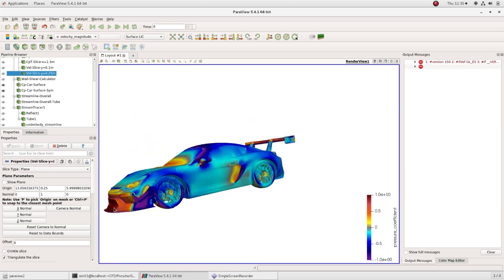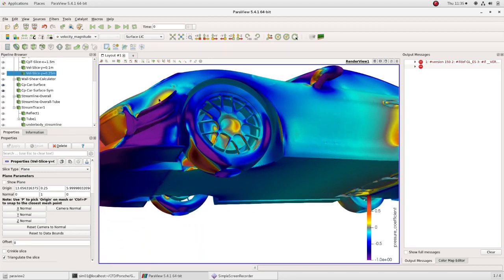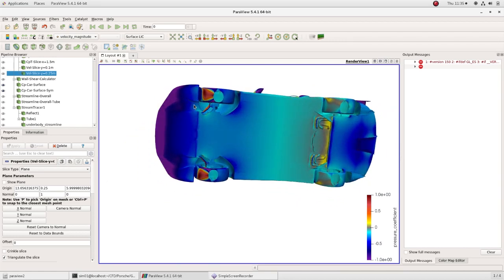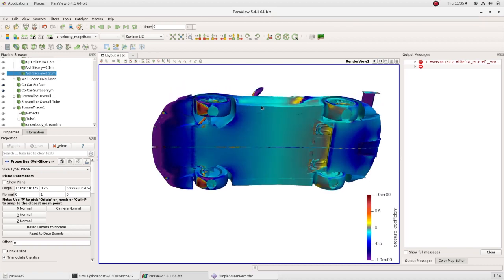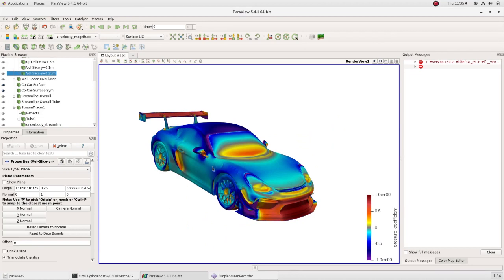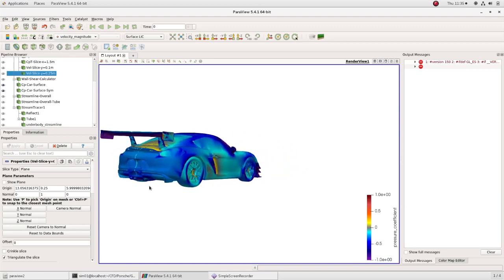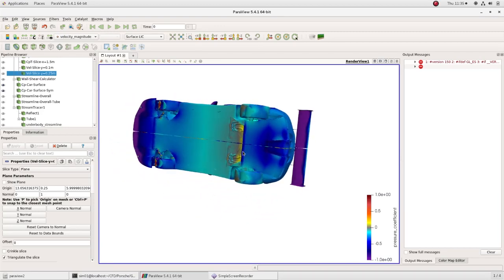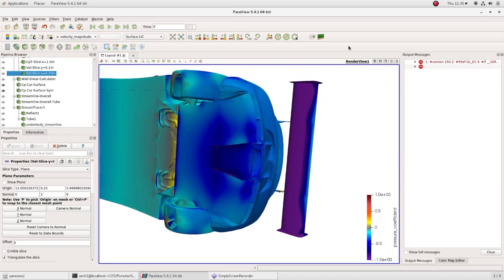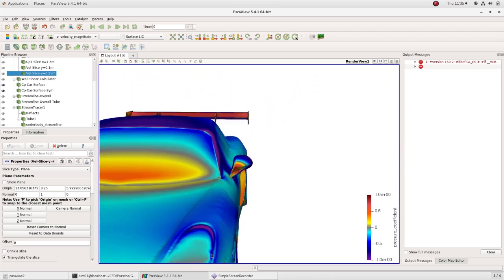The pressure coefficient is a dimensionless number which describes relative pressure throughout the flow field. It is very commonly used in external aerodynamic cases. On the pressure coefficient plot, 0 is atmospheric pressure, 0 to 1 is higher pressure, and -1 to 0 is lower pressure. In our post-processing, the color plot makes it easier to tell areas of high and low pressure. High pressure is yellow to red, while blue and purple is low pressure. Gray is atmospheric pressure, so it would be on areas of no effect on the surface of the car.